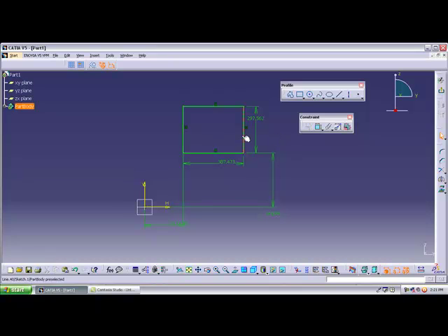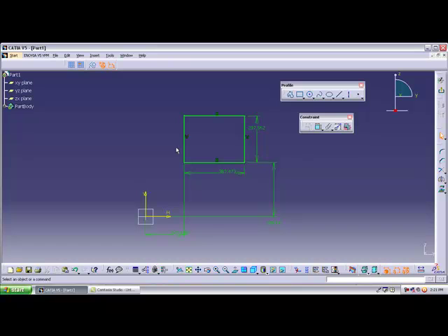See, right now if you try to move this rectangle up, it's not moving. Why is it not moving? Means it's completely constrained. How is it constrained? The rectangle length is horizontally 387 and vertically 297. And where is the rectangle in the plane? Means from the horizontal axis 345 distance and the vertical axis 247 distance. Like this we can make the dimension fixed. We are making the object to a particular dimension and we are locking this object with the dimensional constraint.